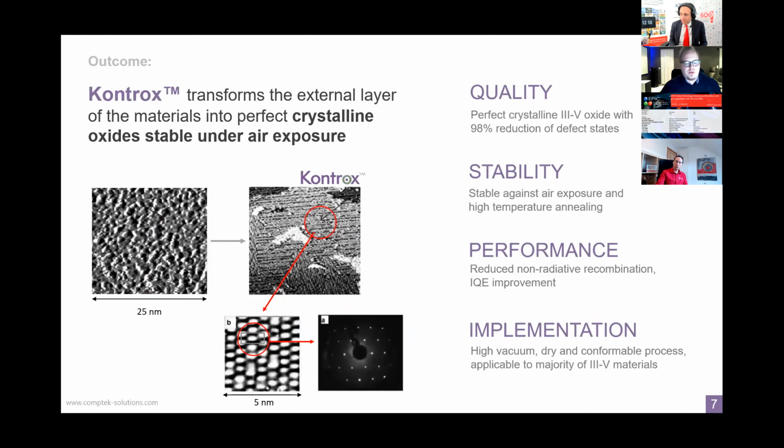So what is Controx? Basically, it's a family of patented processes for different kinds of compound semiconductor materials, where we can transform the surfaces of 3-5s into crystalline oxides, which have very low defect state densities and which are stable. So these structures are stable under air exposure, or ALD process, or against high temperature annealing.